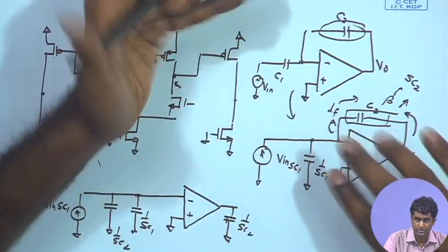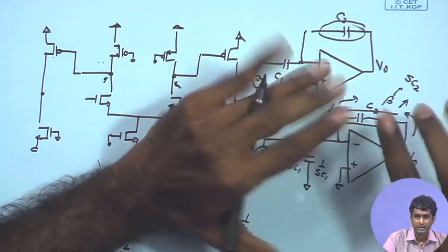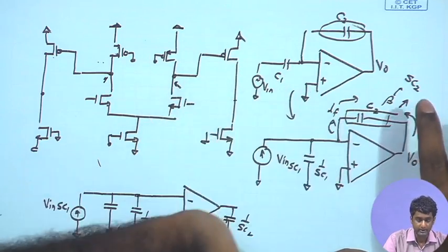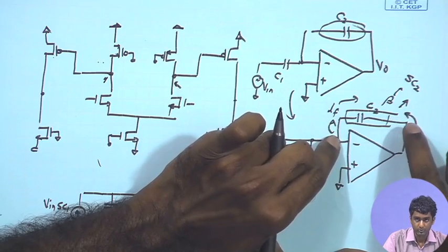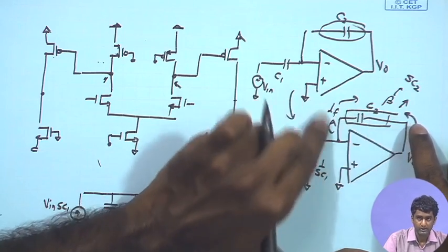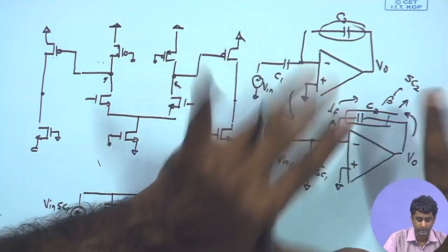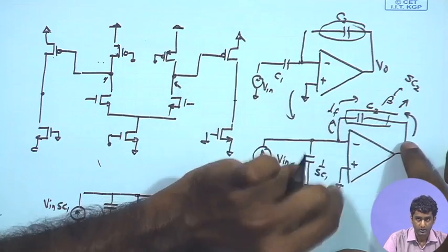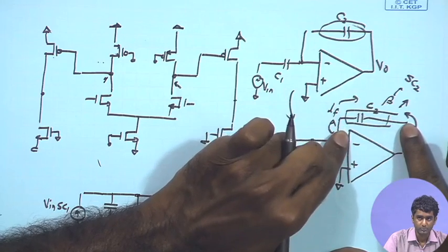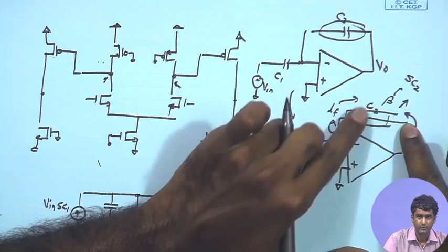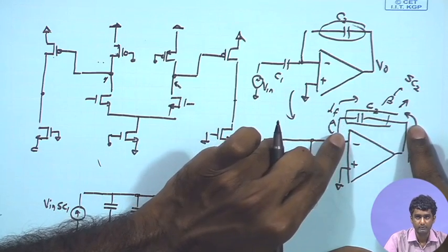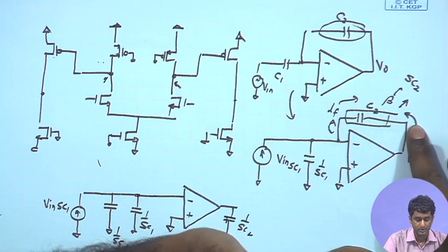Therefore, for assessing the overall voltage to voltage conversion factor, we would open circuit the output port of the voltage to voltage converter, and likewise while assessing the conversion factor for a voltage to current converter like this feedback factor, we would short circuit the output node, so that the feedback network is not loaded by the amplifier. So, we are trying to characterize this feedback network: given a voltage signal over here, what is the corresponding current provided by this feedback network. So, what is the voltage to current conversion factor for this feedback network for the shunt configuration.